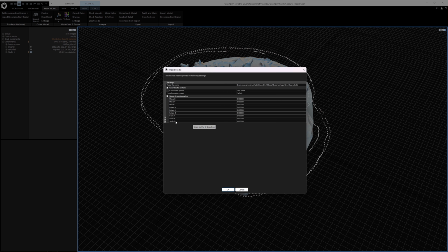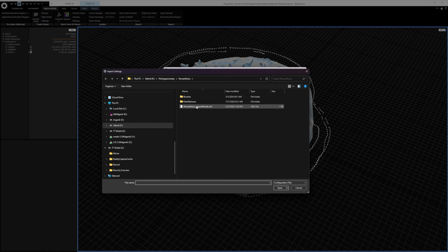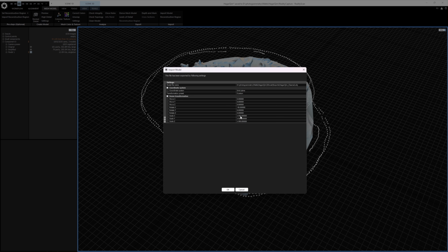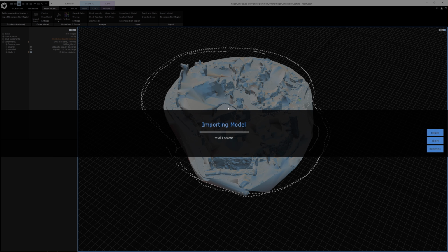This one. So I saved it down to a file. It's this one here. It's something I used before, so at least it does carry over from project to project if you only do the same thing. So this is how it works if you import as an FBX to 3D Coat and export it from there. You got to use these values here, and they don't really make any sense because I'm actually scaling it up 1,000 times and rotating 90 degrees in X, and then it becomes correct. So click OK, and then we just wait for it to come in.